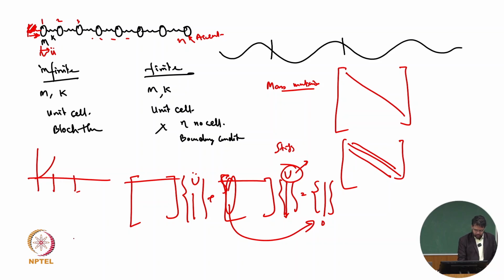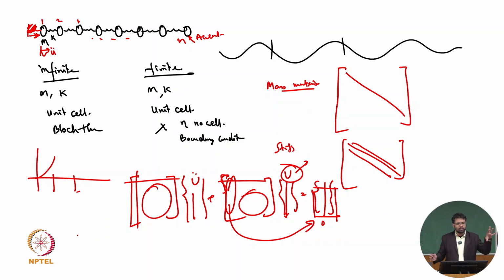So we will now have that condensed portion, and we can solve the mass matrix, the displacement matrix, and the other side, and find out how much displacement we can see in each case.